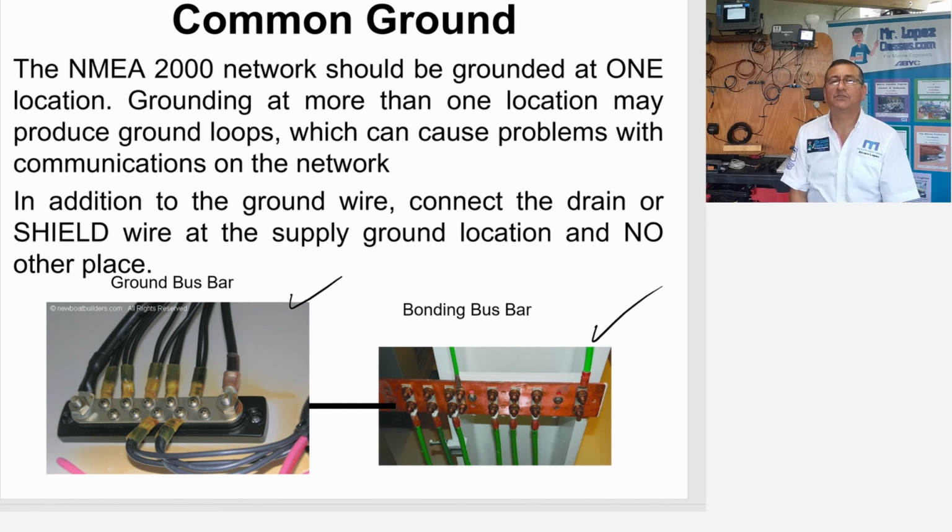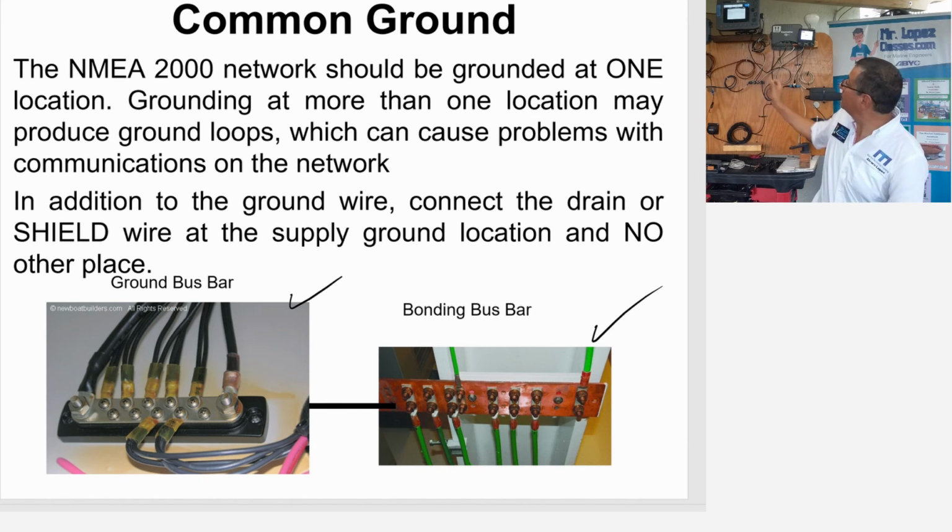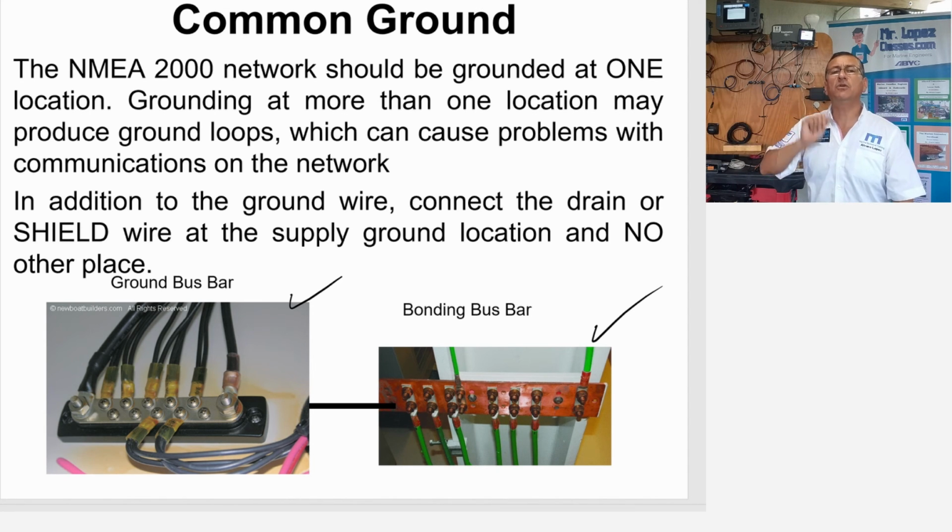90% of the problems that I solved with the backbones are because the customer complains about an attenuation code on the display, and an interference code on the display. And when I visit the boat, immediately I check where the backbone is located. Oh, the backbone is here. Okay, nice. Excuse me, what about that equipment in that corner? Oh, it's a new air conditioning equipment. We installed that air conditioning equipment a couple of weeks ago. Oh, yeah. Okay, my friend, this is the problem.